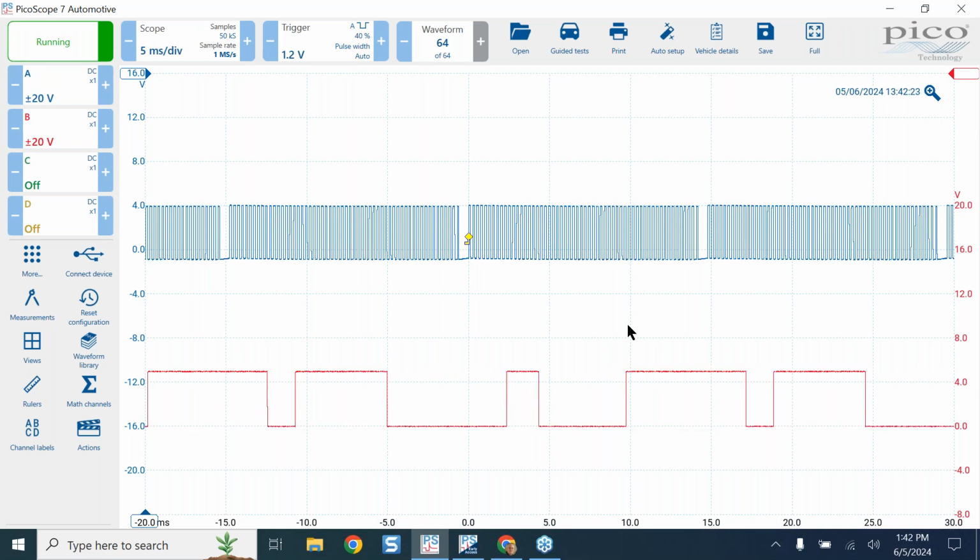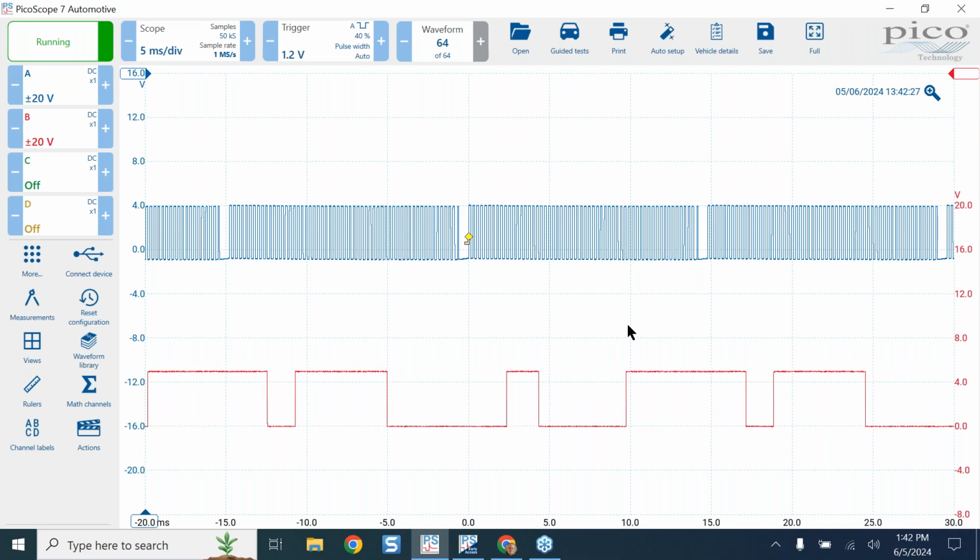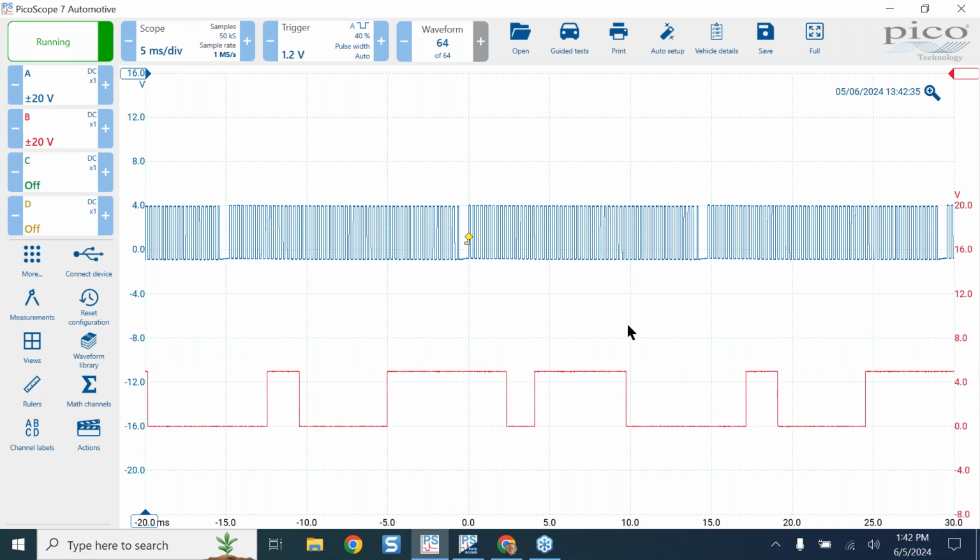Do we have a sensor issue? Or do we have an encoding issue? Possibly the wrong reluctor, the wrong crank, the wrong cam, the wrong engine. I'm sure you've seen them before. I've certainly seen it before, doing mobile for 13 years. They put the wrong engine in it.